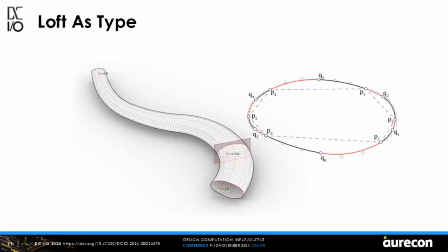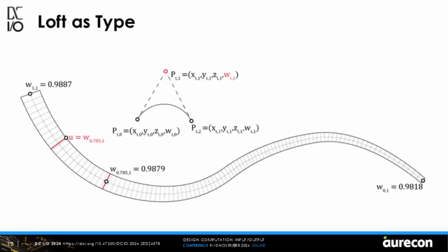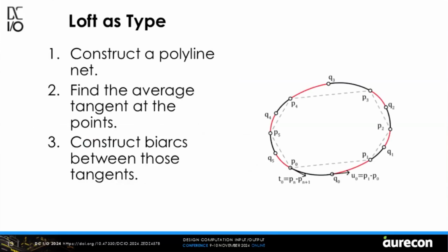What we find is that when we loft something, we end up with a NURBS curve with a set of additional points instead of arcs, and that more points are added in order to get a better approximation. This is in contrast to the possibility where you could manipulate the weight of the point as a way of interpolation. However, the priority is to add more points with weight 1 to get that approximation rather than manipulating the control points, in order to allow for it to be exportable into more software. Sadly, it is outside our abilities to rewrite the laws of mathematics, and thus an arc itself is not going to be interpolatable the way that we desire.